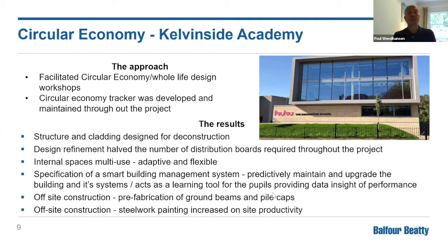Then specification of the smart building management system is something that's always sort of lost or not really fully done. And then you end up with a building management system that somebody dusts the manual off when they open up the project, saying, right, how does this thing work? It's fundamental to make the building efficient in use that you're thinking about that up front, what is going to feed into it, but also how that BMS is going to be used. After many a year doing facilities management, I've seen that all too often.